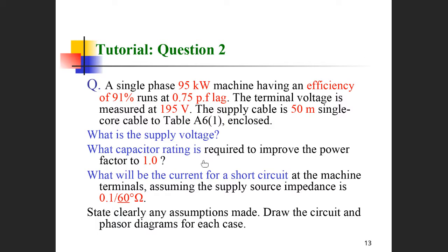And the second part is how to make the power corrections. The power correction is to make the reactive power be compensated by other parts. For example, if you have an inductive load, which usually has inductive reactive power, we can connect capacitive reactive power to the system, so that the total reactive power is small or zero.